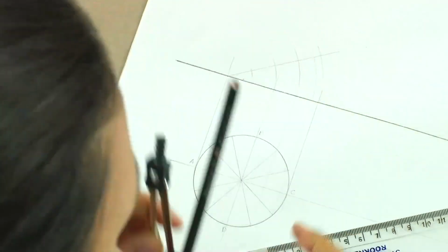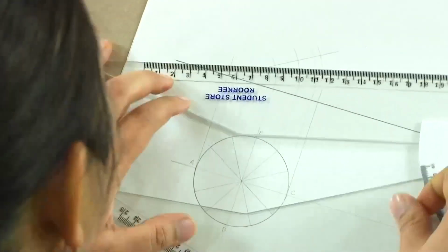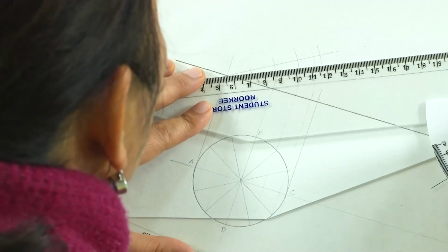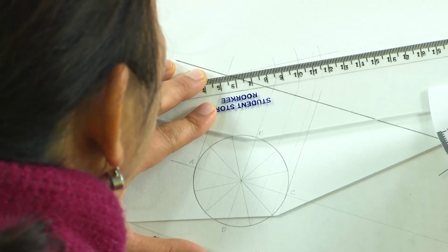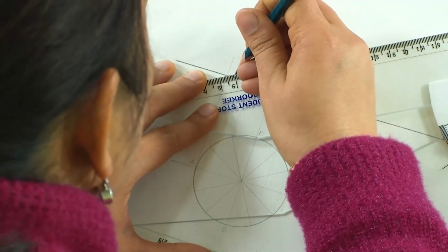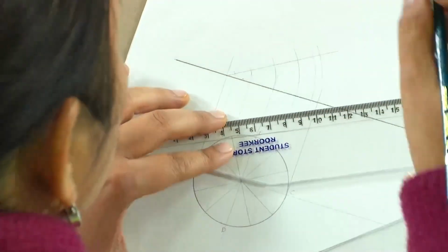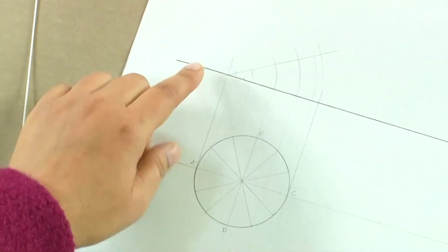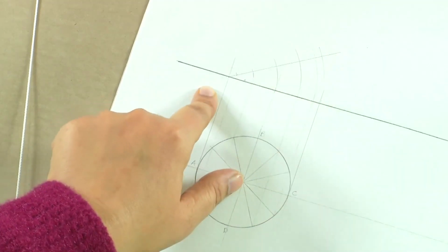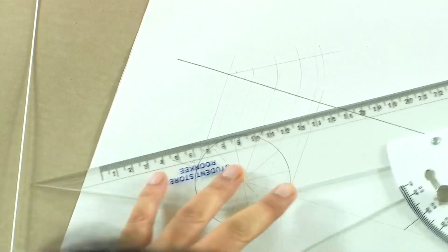So, what we would still see in this case is that the circle still is seen as a line in VP. So, this is the projection of the same circle onto this line in VP, and what we will get back here is an ellipse.